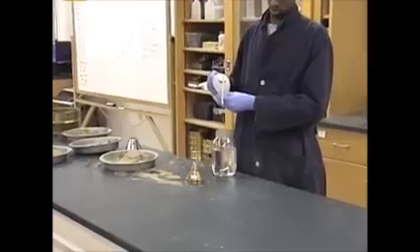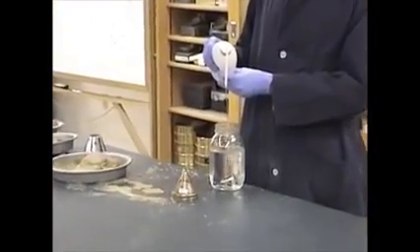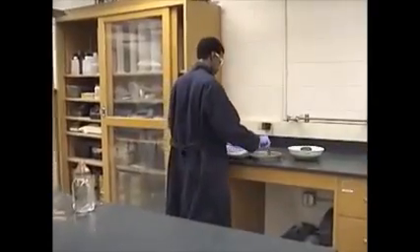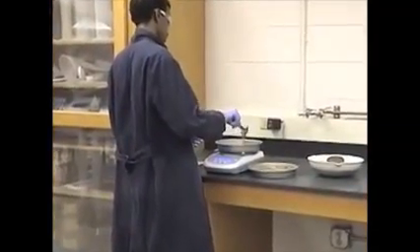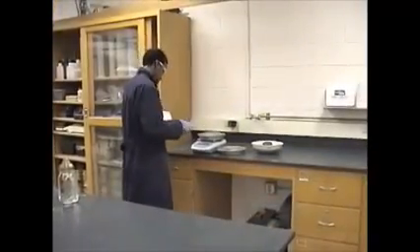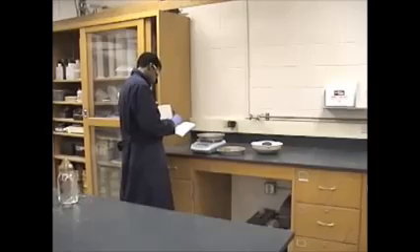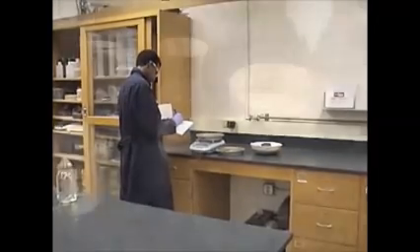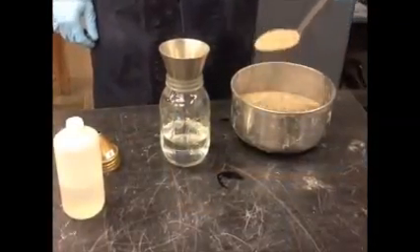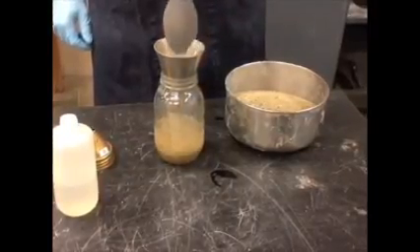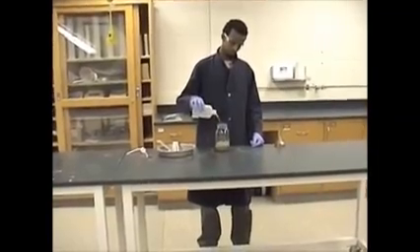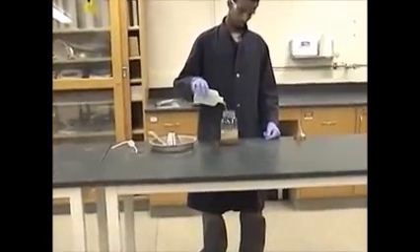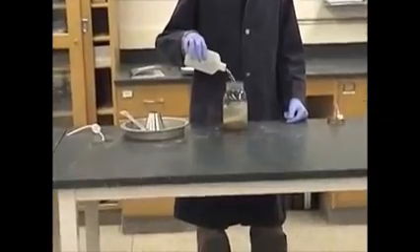To begin our test, we want to partially fill our mason jar with water. Next, we want to weigh out 500 plus or minus 10 grams of saturated surface dry fine aggregate. Be sure to record the exact amount that you've weighed out. We now want to introduce our saturated surface dry specimen into the mason jar. Once the sample is in the mason jar, we want to reintroduce water and fill to 90% of capacity.